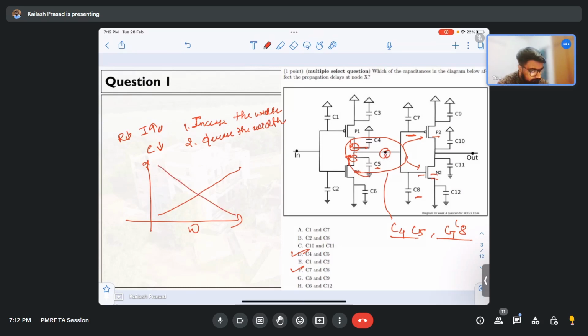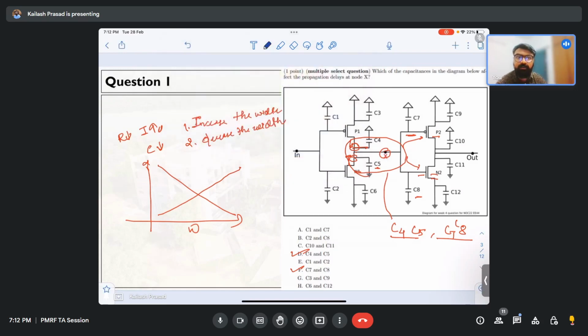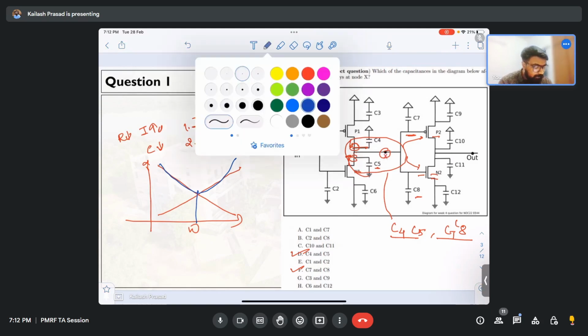We discussed in the last class that if I want to optimize the delay of my circuit, I have to have a point where both capacitance and resistance are minimum. We have to figure out the RC of the transistor rather than focusing on R and C individually. So this particular session is focused on RC delay, because not only R or only C, their individual contribution is not important; rather the combined effect is important for us. And it will affect in a great sense.